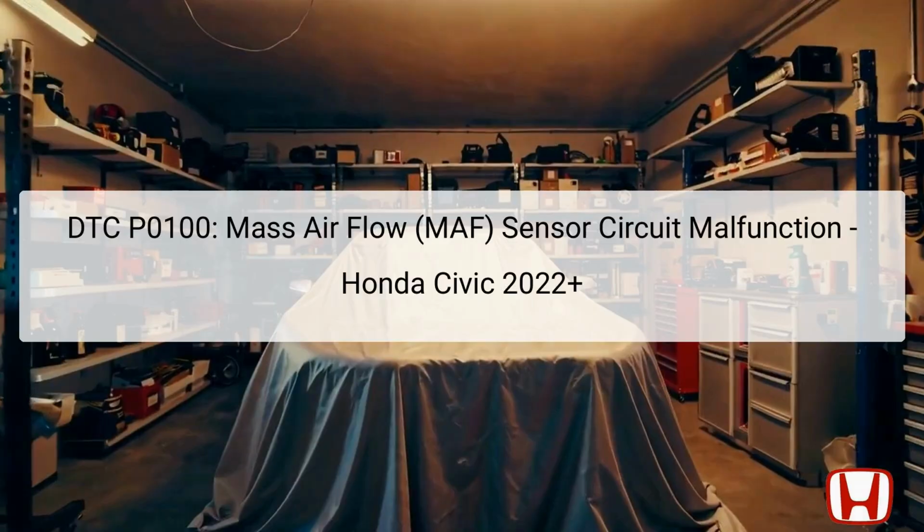The diagnostic trouble code DTC P0100 indicates a malfunction within the mass airflow MAF sensor circuit. The MAF sensor is crucial for engine performance because it measures the amount of air entering the engine, allowing the powertrain control module PCM to compute the correct air-fuel mixture. Located between the air filter and the intake manifold, the MAF sensor provides real-time data to the PCM, which is essential for optimizing fuel efficiency and engine performance.